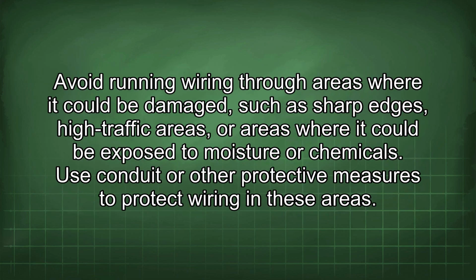Avoid running wiring through areas where it could be damaged, such as sharp edges, high traffic areas, or areas where it could be exposed to moisture or chemicals. Use conduit or other protective measures to protect wiring in these areas.